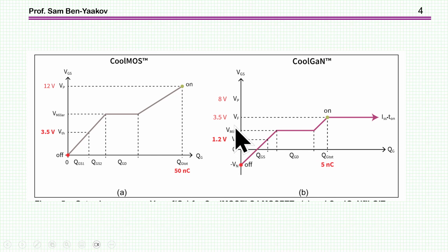And also the threshold typically will be lower. It'll be like 2.5 volt, rather than the, say, 6 volt that many silicon MOSFETs show, although there are some, of course, with lower threshold. So at any rate, the general shape is very similar, which means that the drive requirements are not that different. I mean, they are different maybe in the magnitude, but not in the nature of the requirement of a current pulse during the turn on and turn off.